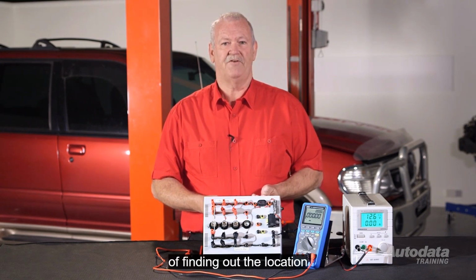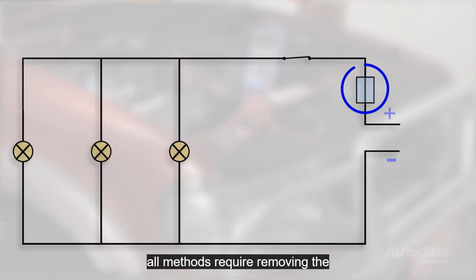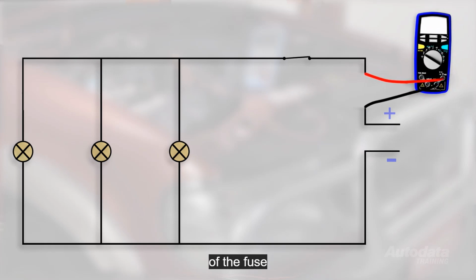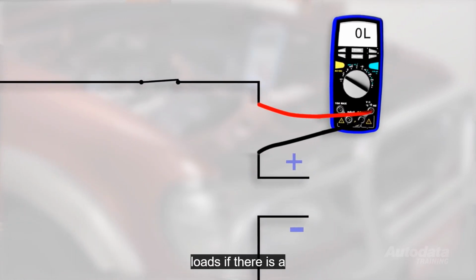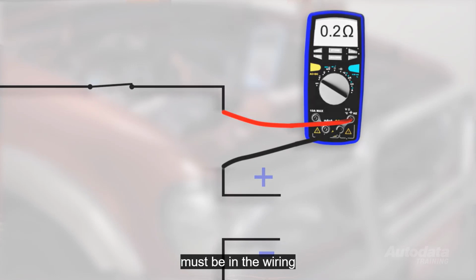There's several methods of finding out the location of the short circuit. All methods require removing the fuse. In the first method, we'll use an ohm meter. Connect the meter from ground to the circuit side of the fuse. Now remove all of the loads. Turn the circuit on and check the resistance. If the meter reads open circuit, then the short circuit must be in one of the loads. If there is a low resistance, the fault must be in the wiring.